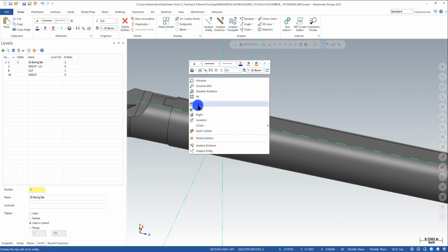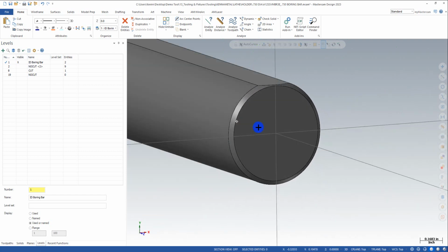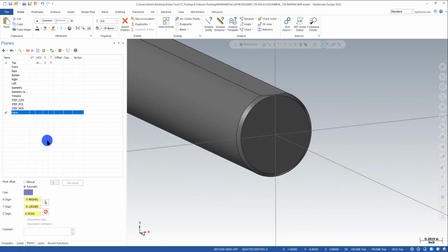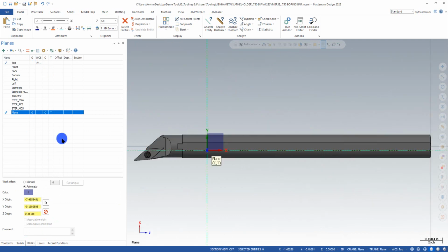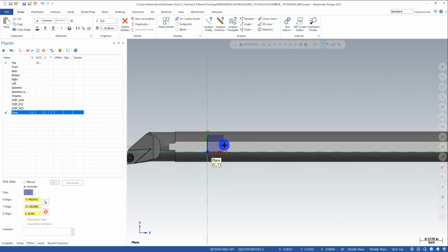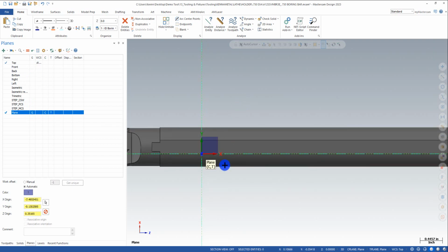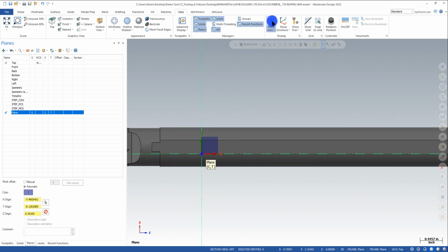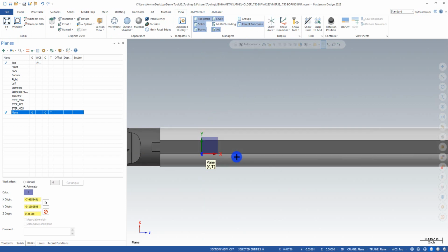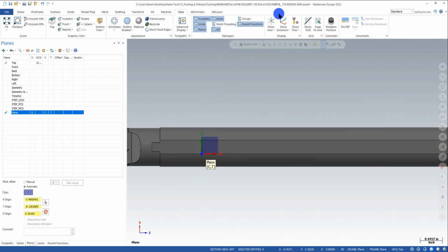Next, I'll go to that top view that we have, but it didn't change view. So you want to make sure that when you go to your plane, you hit that G view right there, and that'll get you nice and straight. Okay. I don't really need it, like I said, as my WCS, just my construction plane and my tool plane. If you don't like to see the crosshairs, just turn that off as well. I'm not worried about the location of the gnomon either. Matter of fact, I can turn that gnomon off just by going to a view and turning that off.